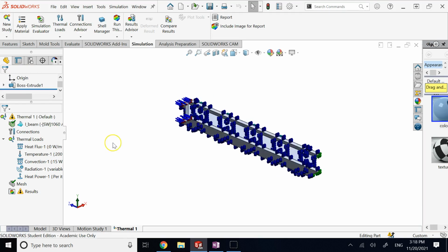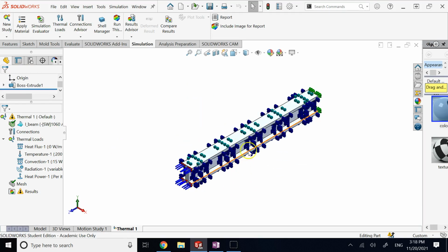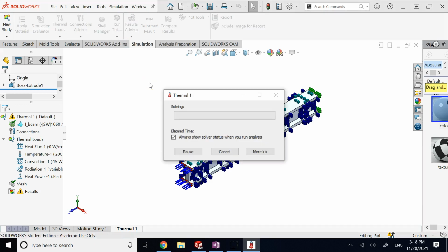So now it is a heat source, a heat power that is also created from the bottom, and it's like you're heating the bottom of the beam. So if that's the case, and if I run the steady, now what would you see different compared to last time that you had the radiation on the top and the bottom was insulated?